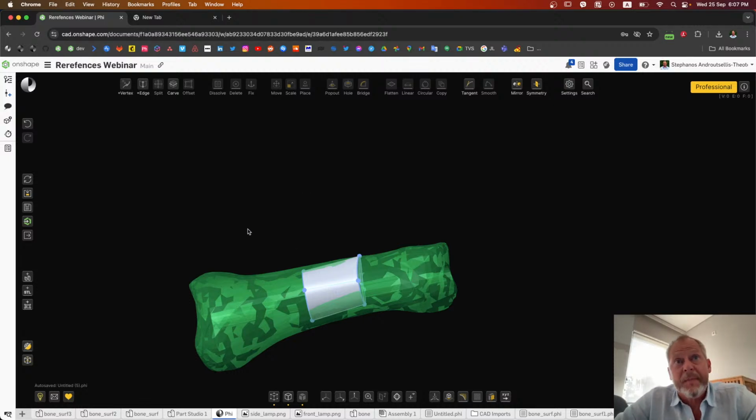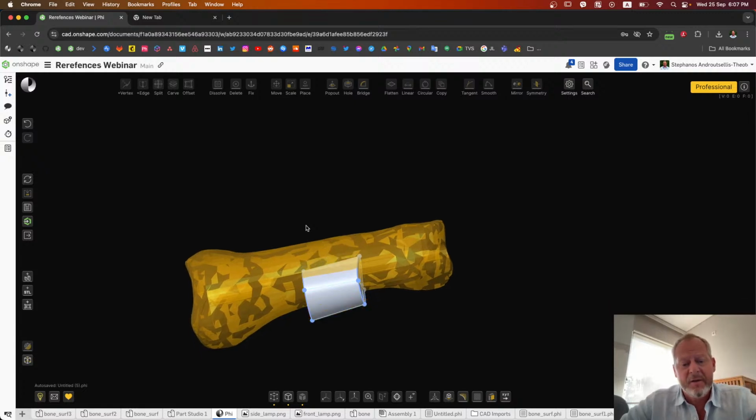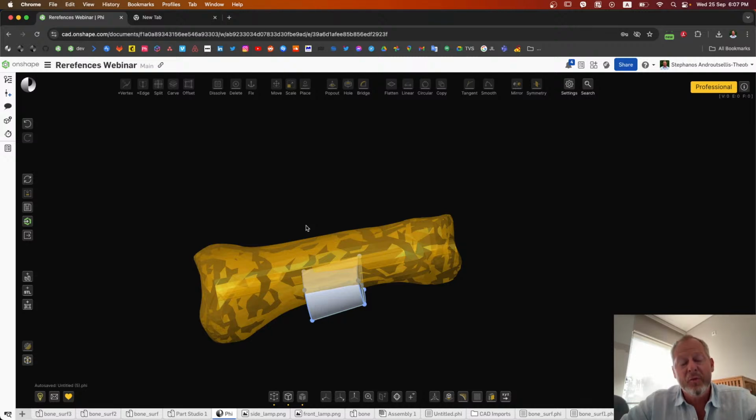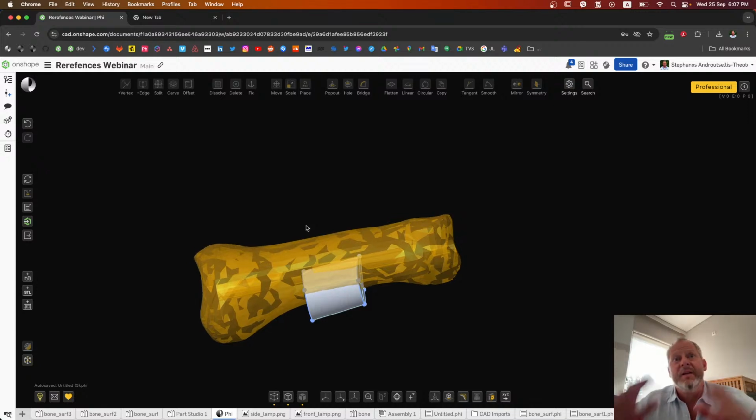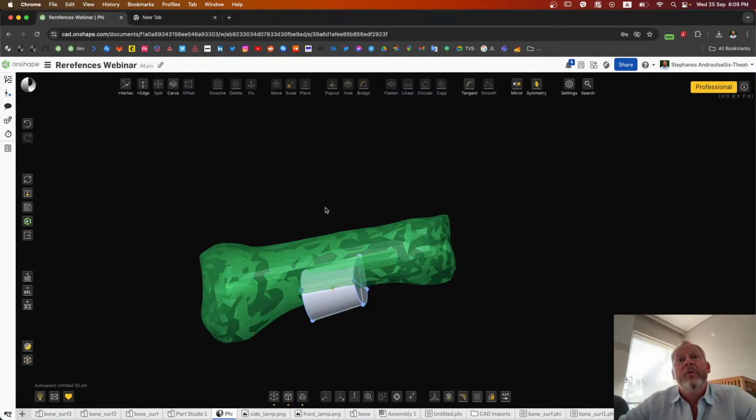All right, now the other thing you can do, of course, from the menu here, is edit the STL model. So I click to select it, and then as we have discussed in the past, you can use the X, Y, Z buttons to move it, and 1, 2, and 3 to scale it in the three dimensions, or the up arrow and down arrow to rescale it proportionately. And then when I'm done, I exit. Again, there is some lag. Okay, I exit the edit state, so now my model is there.